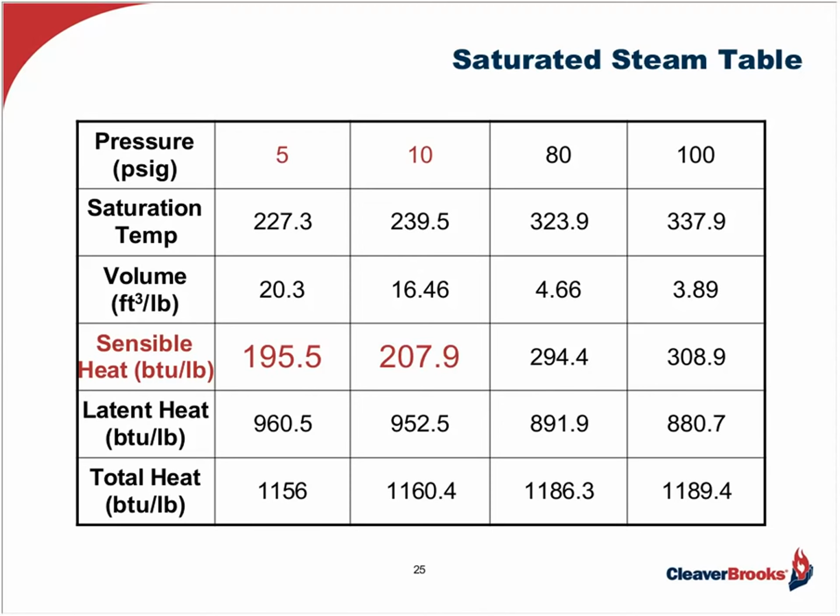So then, referring to the chart on the screen now, notice the amount of sensible energy required to convert a pound of water to a pound of steam at 5 or 10 pounds of pressure. And this is a typical steam table based on a 32-degree incoming water. Point is, if I can raise that feed water temperature coming into the deaerator by returning more hot condensate, I can reduce the sensible BTU requirement from my boiler's burner to make the required amount of steam to reach the saturation by a ratio of 1:1.